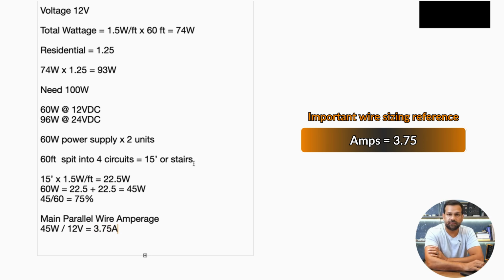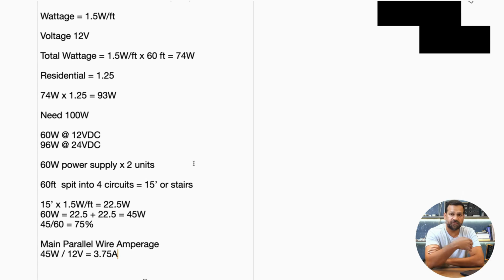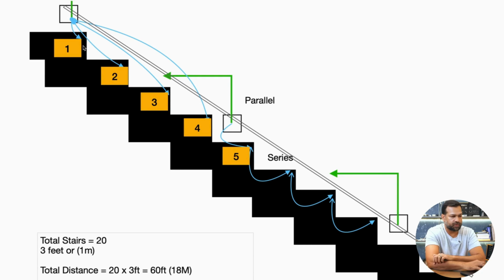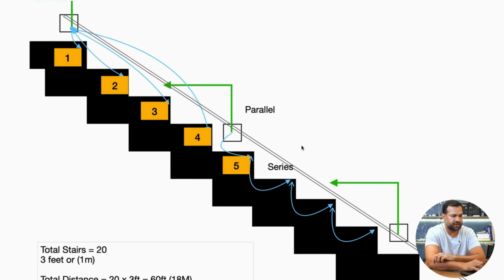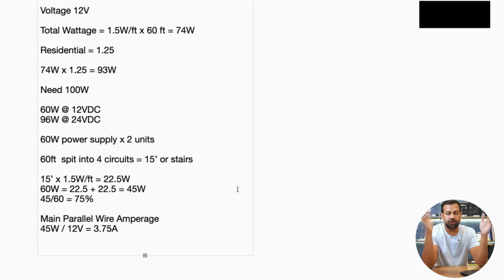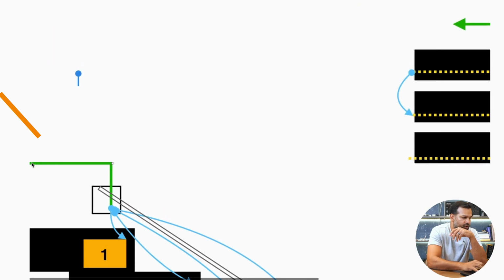which is really small. However, if you have to factor in voltage drop, you want to look at probably 11 volts or probably the wattage you'll get at this area here. That's really small. So you now have to determine what gauge wire is going to be used, this main green wire across here. And you would just use your voltage drop calculator.